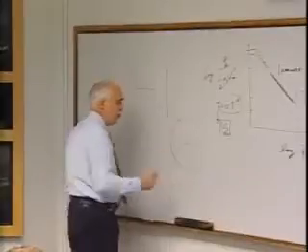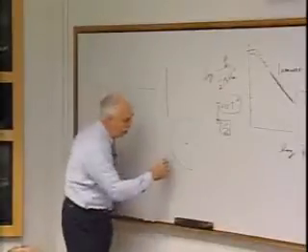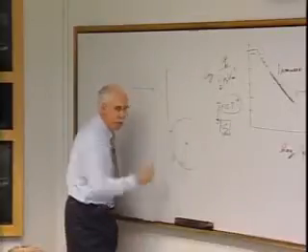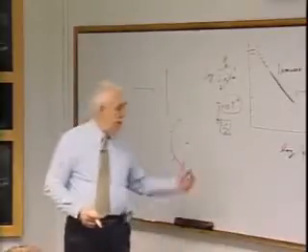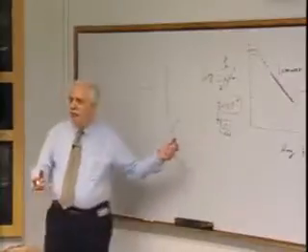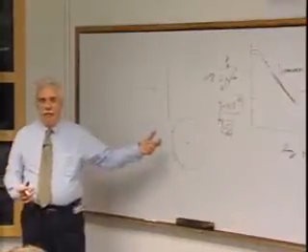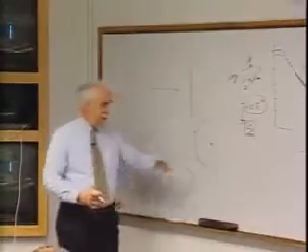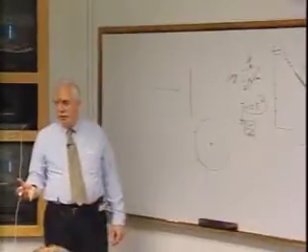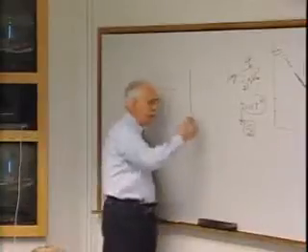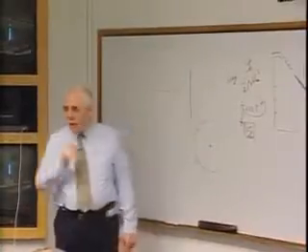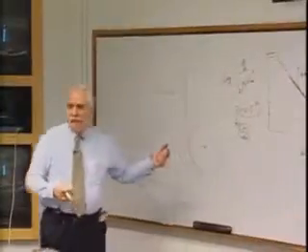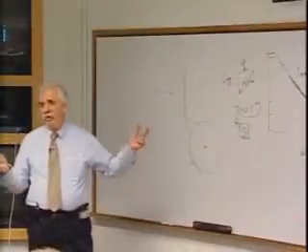Now, the center of pressure, no matter where the pressure is on the vehicle, no matter what the pressure is, it goes right to the center, okay? And that's probably also about the center of gravity if I flew a sphere. Certainly if it was solid, but if I built a spherical spacecraft, it would be neutrally stable. Well, that'd be great. I could spin it and distribute the heating over the entire thing. As I enter, that happens to some meteors. Well, it's not too comfortable, and I don't have control, and I also generate a little lift. There's all kinds of problems with that.